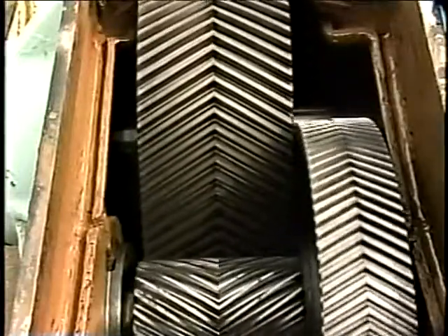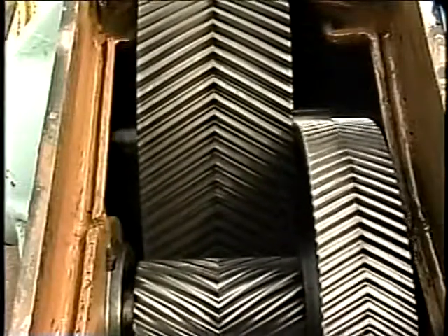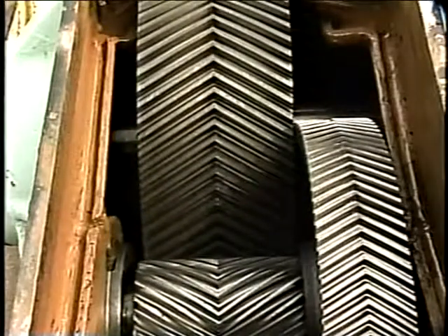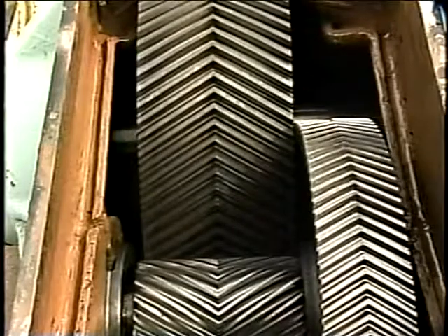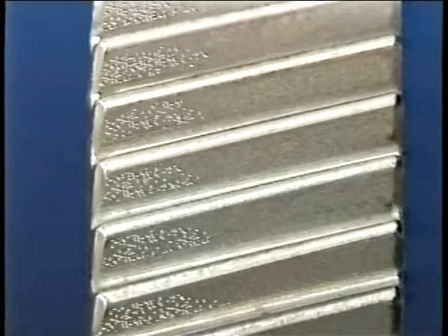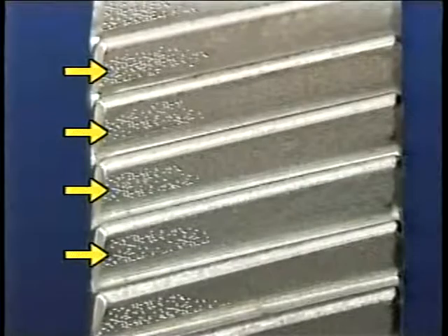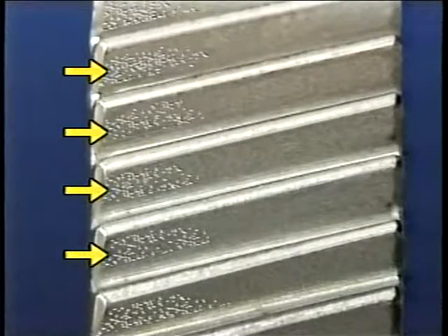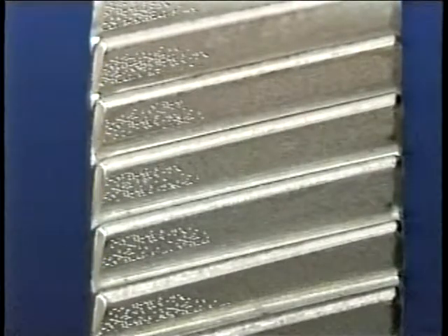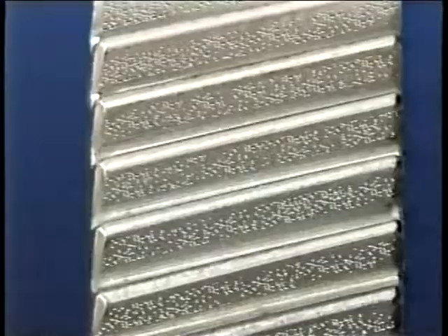Pitting is the result of a couple of different conditions. For example, it can be caused by a difference in the hardness of the metals used when gears are manufactured. Pitting that's caused this way is generally out of the hands of the technician. However, another cause of pitting, which the technician may be able to do something about, is misalignment. This helical gear was misaligned with its mating gear. Helical gears that are out of alignment will start to pit at the leading edge of the gear teeth. Pitting starts at the edge of the gear teeth because the load isn't distributed evenly across the teeth. It's concentrated on the edge. If the problem is not corrected, the pitting will gradually spread across the entire width of the gear teeth.